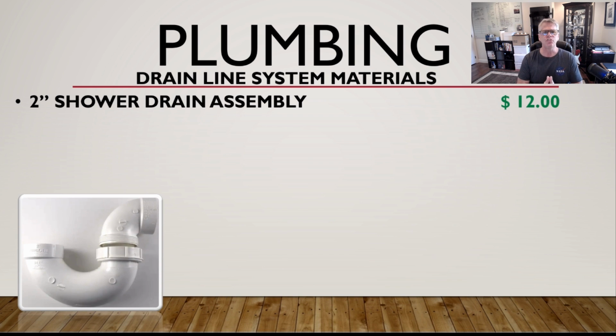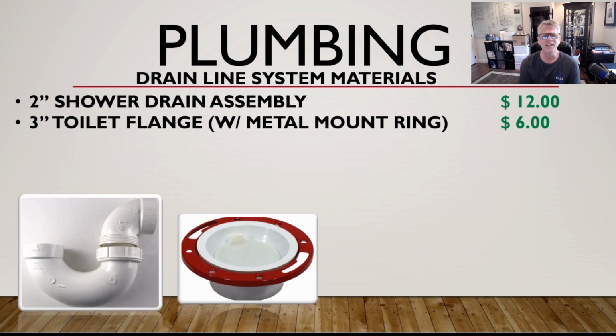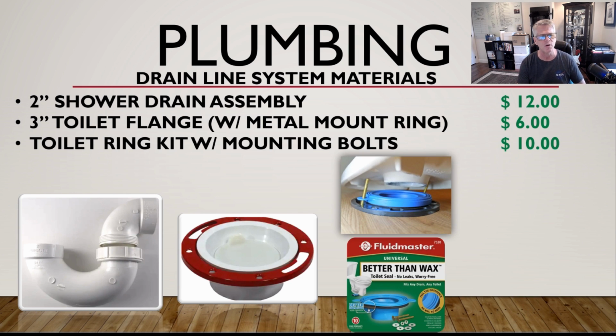Then you'll need a 2-inch shower drain assembly, about $12 for that. That'll be going in the floor underneath your shower to trap your shower drain. You'll need a 3-inch toilet flange, a 3-inch with a metal mounting ring. I like the metal mounting rings. I got the PVC mounting rings as well, but I find that the metal mounting rings are more versatile and they're stronger. $6 for one of those.